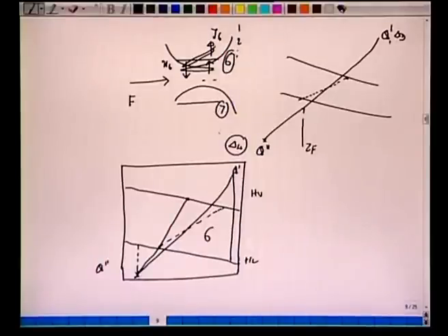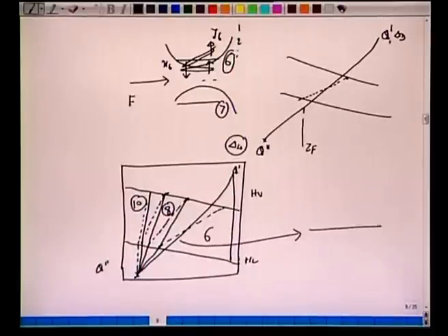Now we are in the stages in this stripping section, and here we have to do the same thing. Now we have this tie line, we connect here, take this liquid tie line, so that would be stage number 8, connect with this to obtain here. Now another mole fraction, we take a tie line, stage 9, and we connect here to obtain this. This will connect finally to our bottom product as stage number 10. So whatever operations we have done for the rectifying section, we are doing for the stripping section. And here we have the same mechanism, same scenarios.